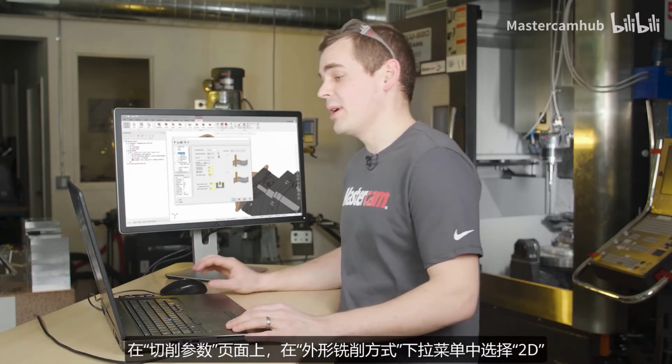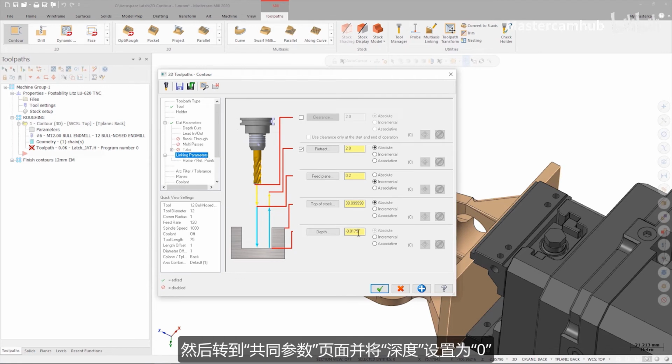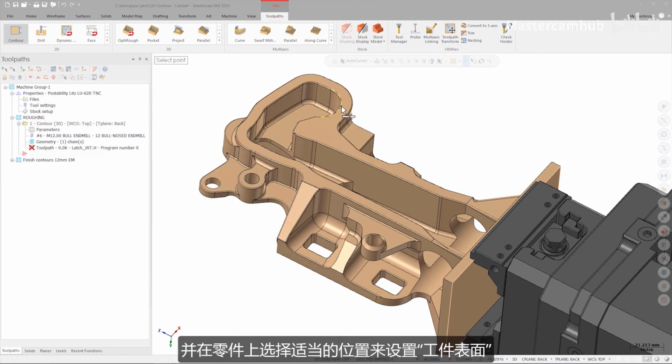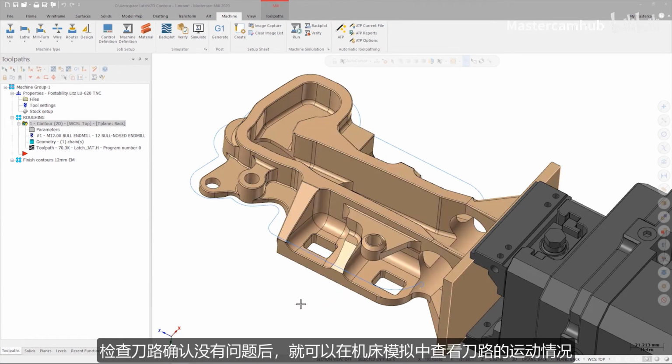On the cut parameters page, I set the contour type dropdown to 2D, then go to the linking parameters page and set the depth to Z0. After this, I can set the top of stock by clicking the top of stock button and selecting an appropriate auto cursor position on the model. Next, I can click OK and let Mastercam generate the toolpath. Once I inspect the toolpath and am satisfied with the result, I can launch machine simulation to view the toolpath in motion.